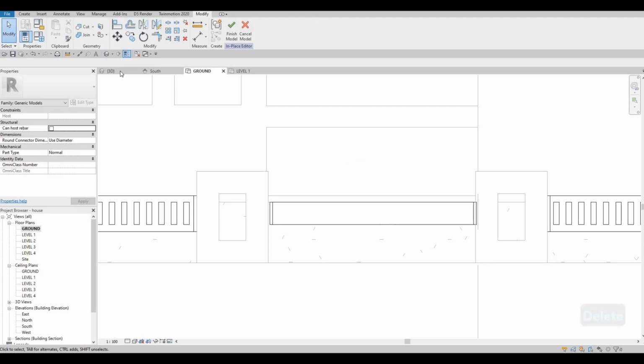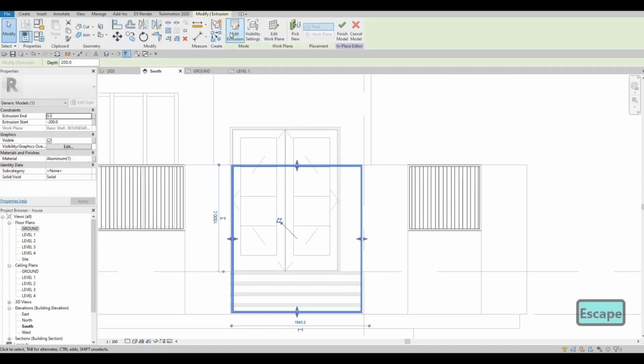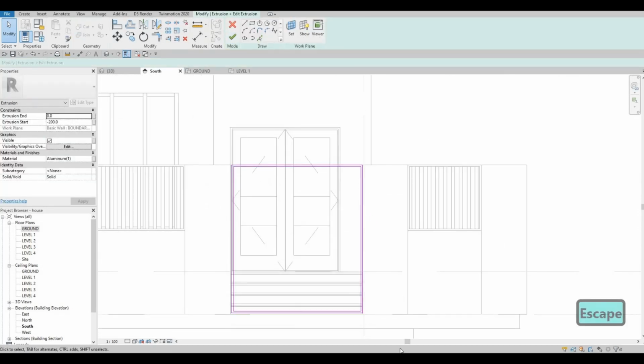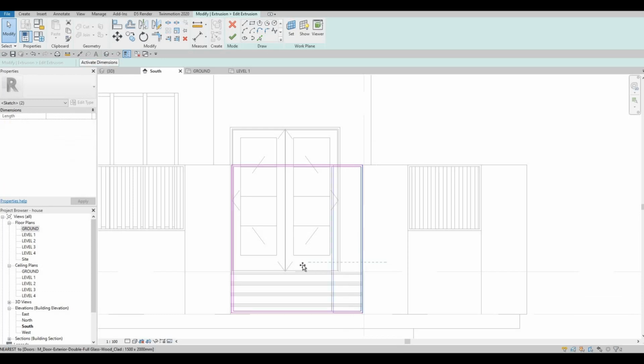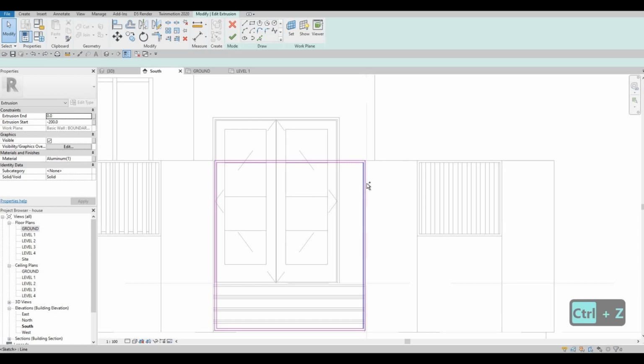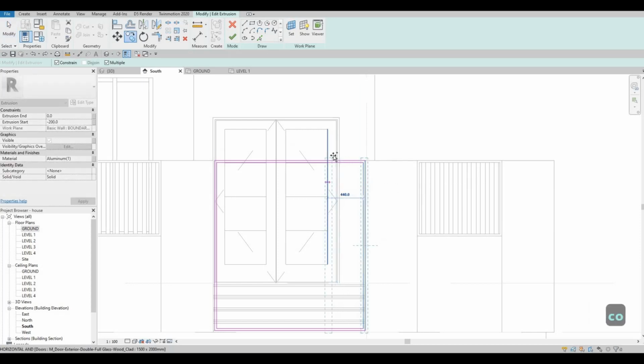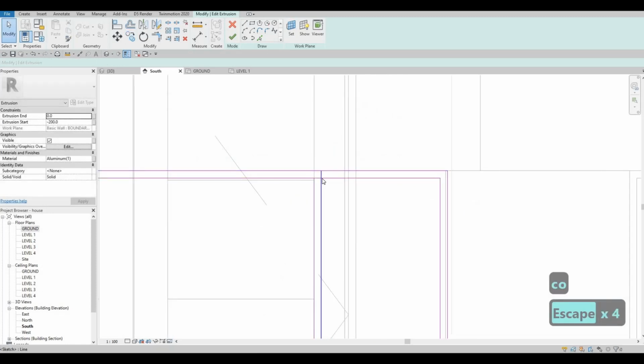end this extrusion. I actually want to go back to south, going to edit this extrusion. Don't worry, it's going to be an easy addition. I just want something like this, or just another line. I'm just going to copy this, CO, something like this, and then we just need to SL, split element on this, and TR.